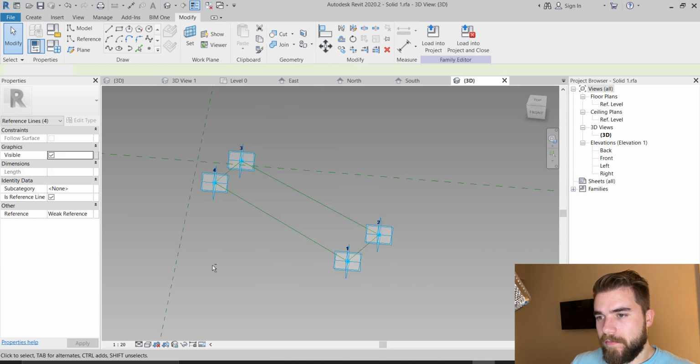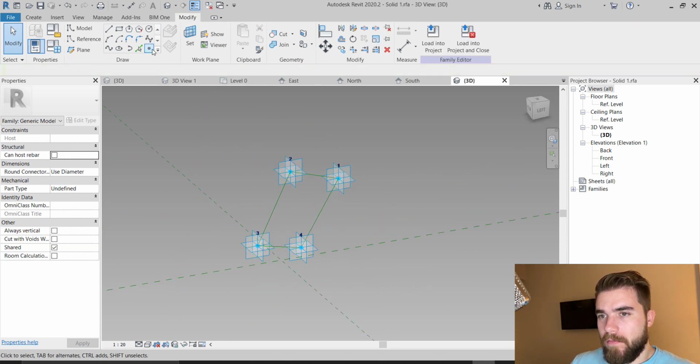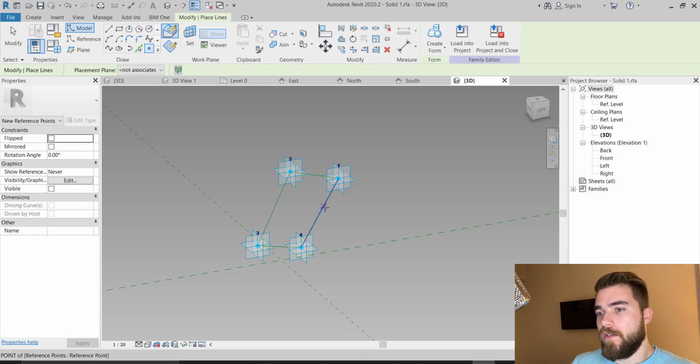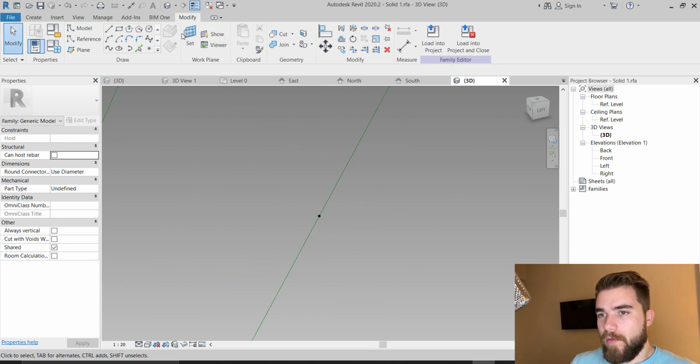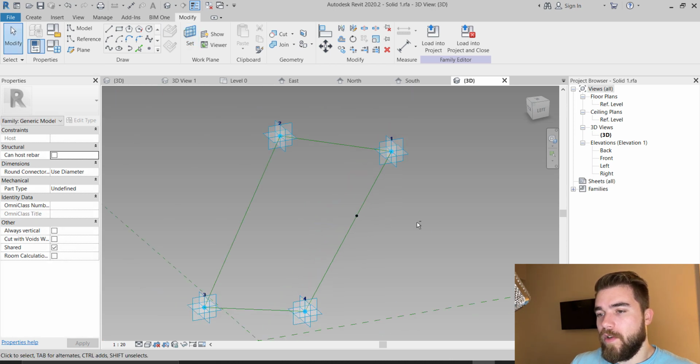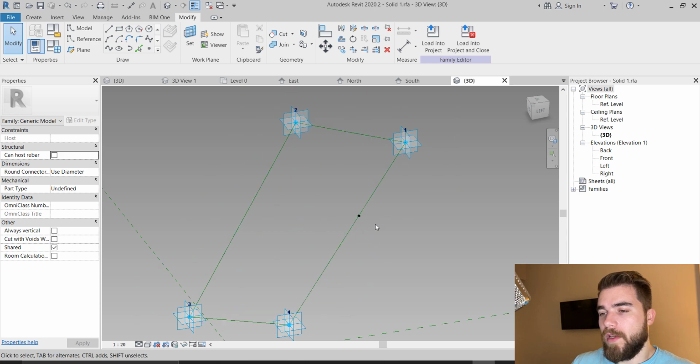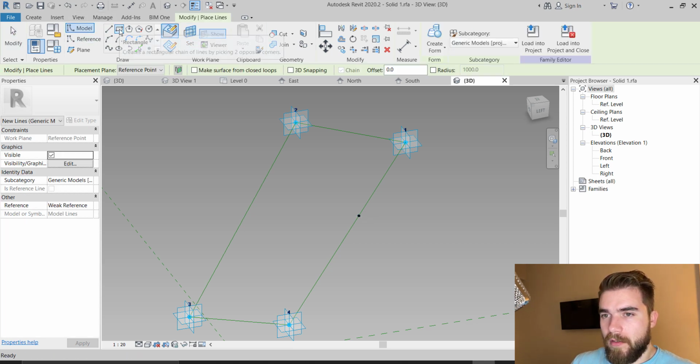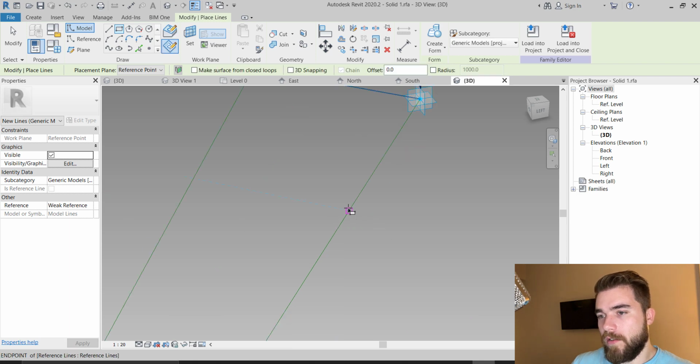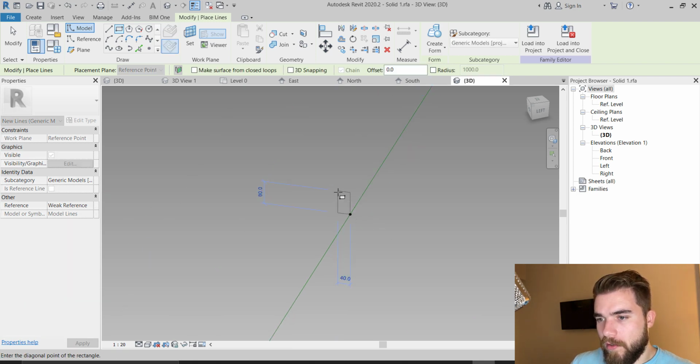So how to do this? I'm going to create a point on one of those lines. Then I'm going to set this point reference plane as my drawing plane, like this. Set, and click on that plane. Then I'm going to go to the rectangle tool, and I'm going to change from drawn face to drawn work plane, because this is my work plane now. I'm just going to create a profile,